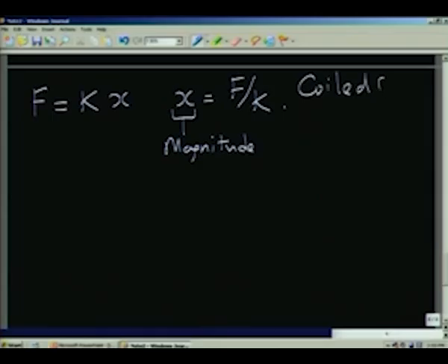What we showed earlier is a coiled spring made of a suitable material, and usually you should not allow the spring to extend too much because it may undergo permanent deformation. So that is very important. If you subject it to a load which is too large, it may actually undergo a permanent set, and therefore it becomes a useless instrument. Therefore one has to remember that there is a certain maximum value of force or weight which you can measure with a particular spring.